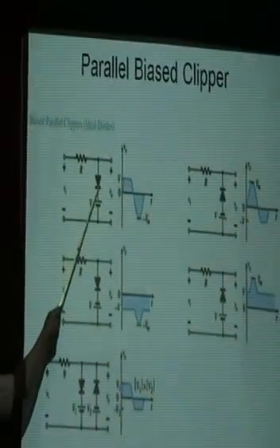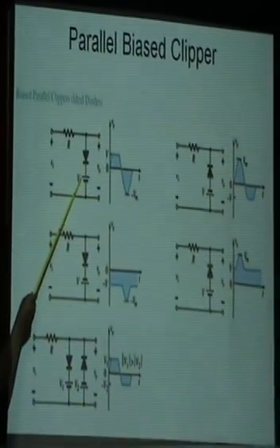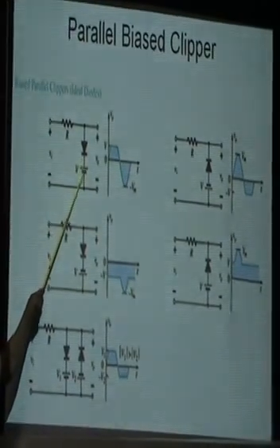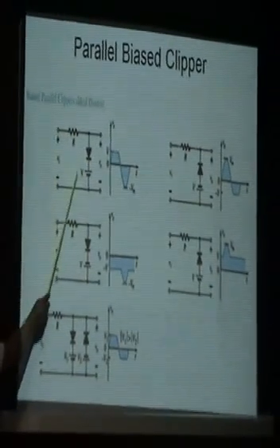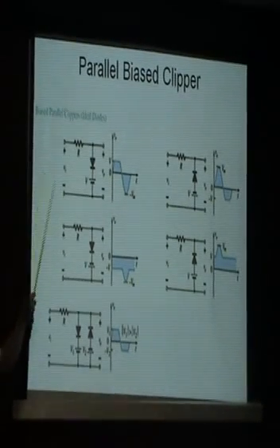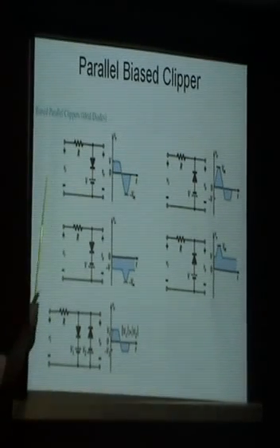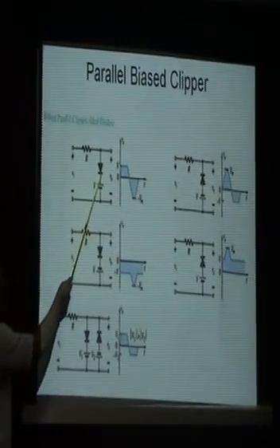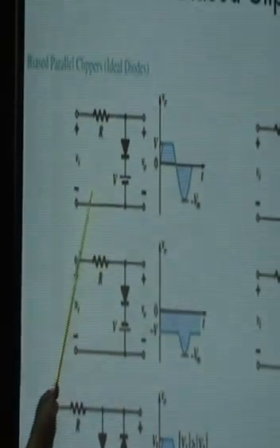This figure shows this is the P terminal of the diode, this is the N terminal, this is the positive terminal of the battery. That means this battery opposes the system. That means this battery doesn't want the diode to conduct. Again the input is a sinusoidal sine wave, positive half from 0 to pi and negative half from pi to 2 pi. For the positive half the polarities are positive here, negative here, which can forward bias the diode. And if the diode is forward biased, there must be a conduction of current.